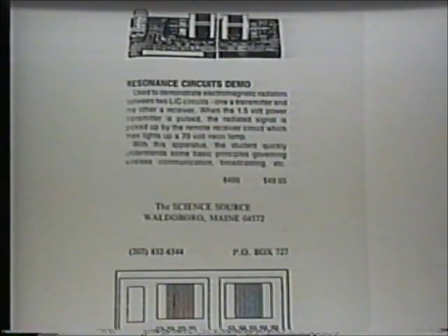Okay. When you get into building the Tesla coils proper, basically what you're doing, you're energizing a smaller coil, which is your L1 coil, and causing a larger coil, which is your L2 coil, to react. And it's the exact same system there, except that it's put into a more compact and convenient system. Now normally the L2 coil would be some distance, maybe 3 times the diameter of the L1 coil, but that's not really necessary. It can be smaller than that.